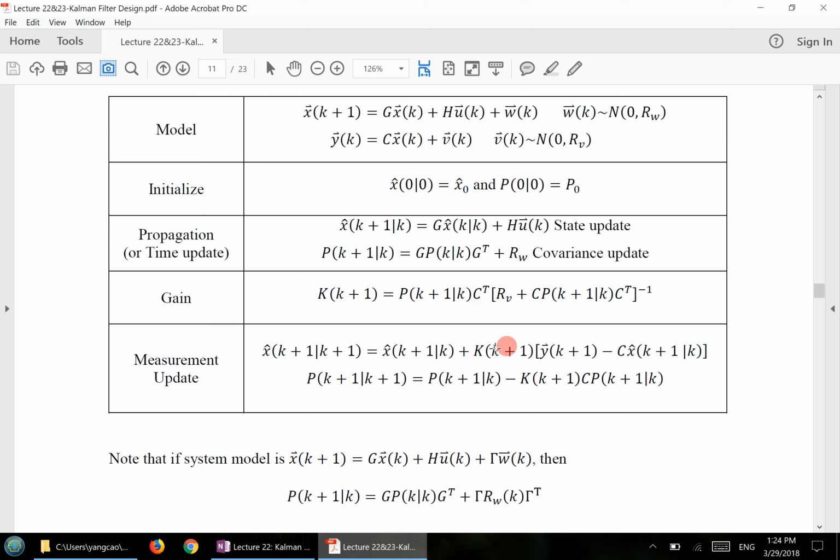You're required to use a gain to multiply by this difference. Would you choose a bigger gain or a smaller gain? Smaller, right? Because you know this is so noisy, and you don't want to amplify the noise by multiplying it by another value. That makes sense, right?